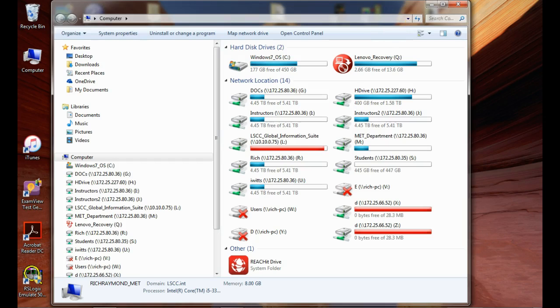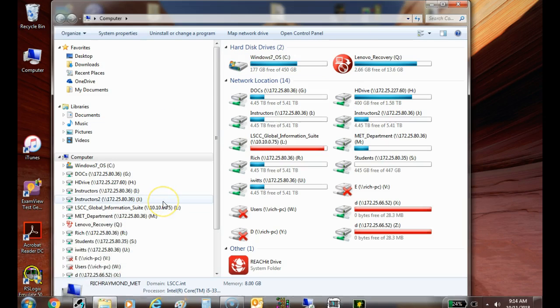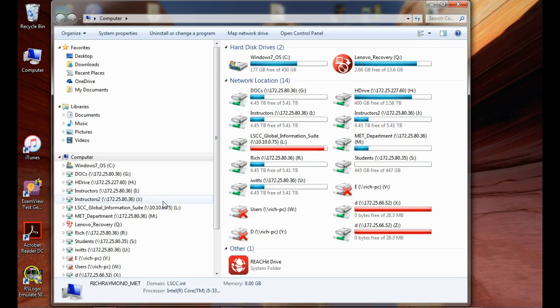The next thing we would do would be what? Choose a filter. Try to choose the right capacitor that would be able to run the load between those humps on the output of our power supply. So that capacitor is literally running the load, right? Between the humps on the pulsating DC that we get out of a rectifier.